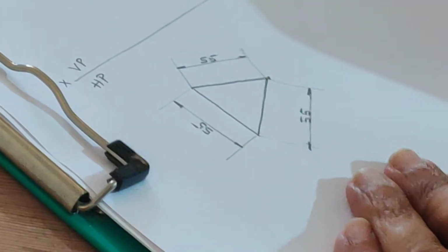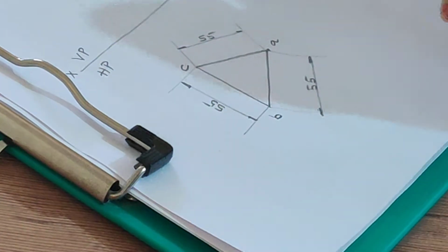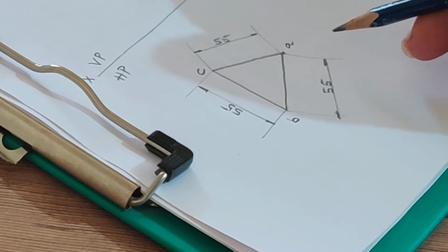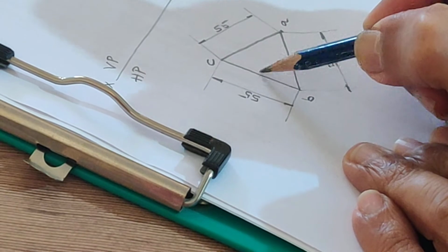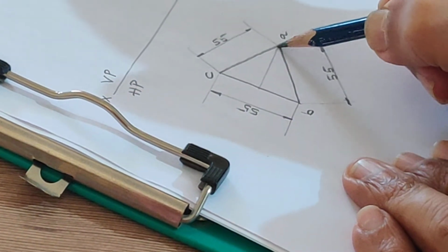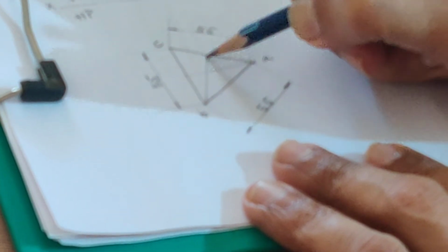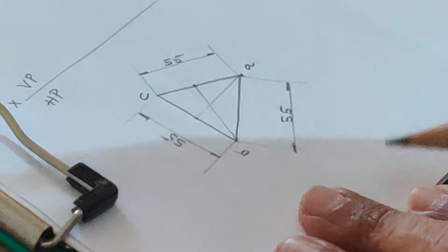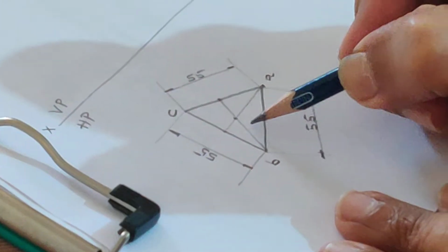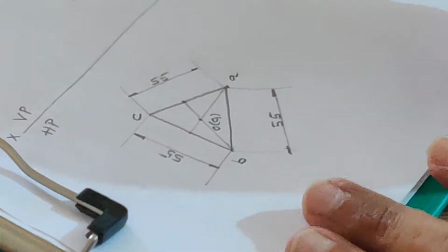Now this is like a pyramid, as I said. So we are going to name the corners just by one point, just A, B, C. You won't get A1, B1, C1. Now let us find out the apex. To find the apex, you should find the center. For that we will draw perpendicular bisectors for any two edges. From the corner, connect it with the midpoint of the opposite side. From this corner, connect with the midpoint of the opposite side. Wherever they intersect, you get the center. That itself is the axis.